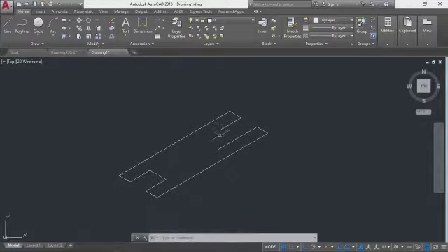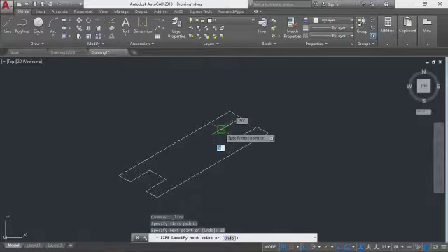But for you to do that, probably you can just cancel this so that you understand. You pick your line and you draw it just the same way you draw this. 25, enter, and you join this line. You escape. So you have to offset this by using your copy tool up. This is your copy tool.